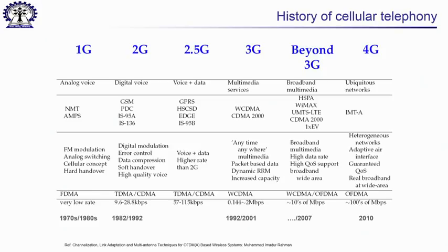One of the major changes that happened over the periods was the frequency reuse factor, which was initially a large number, then finally it came down to frequency reuse of 1. And although OFDMA systems are of frequency division multiple access nature, they are still capable of using a frequency reuse factor of 1 in order to provide very high spectral efficiency, because additional higher layer methodologies bring into account interference management techniques which help it survive.